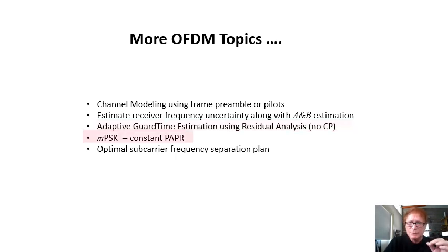The peak to average power ratio is an issue for OFDM. An MPSK, or phase shift key only solution, may be a useful method for managing the PAPR. That is, all subcarriers will have the same amplitude.